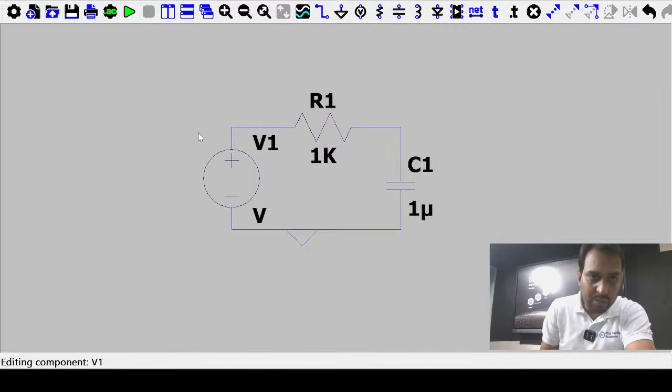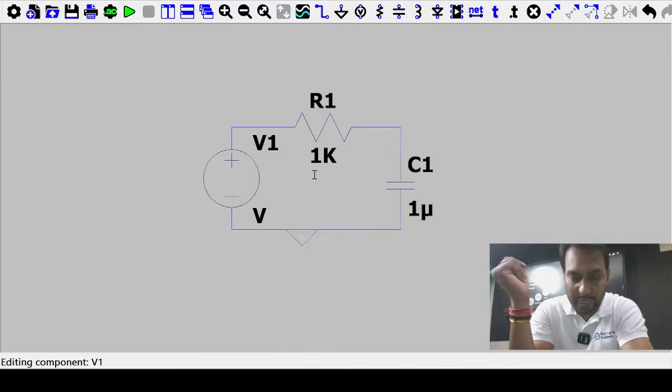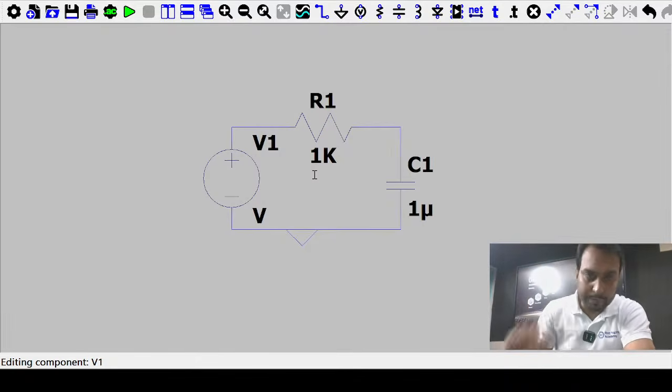So I am starting with the pulse width logic, because I am generating our own waveform, because as per the time dependency we want that your input till T1 is 0, after T1 becomes 10 volt suddenly and it maintains 10 volt. So that's why you require your own waveform, that is pulse width logic.